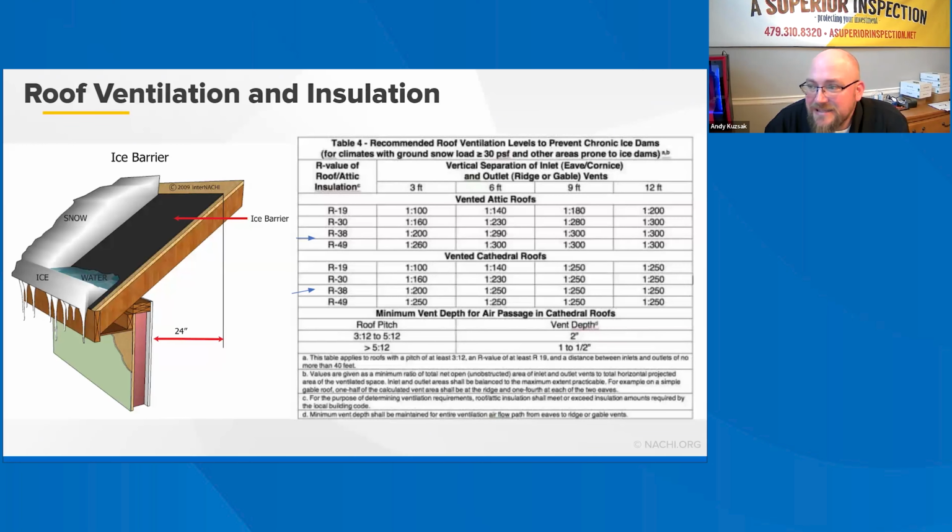And in the case of ice dams, elevated attic and roof temperatures during winter can cause snow on the roof to melt. Insulation and roof ventilation help to keep the roof's exterior surface cold and to help minimize the development of melted water and consequently ice dams.